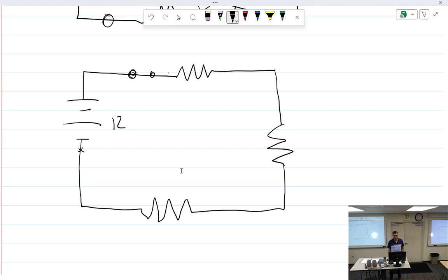But if we're measuring it from here to here, then we're measuring voltage drops: the difference between what the voltage is over here in this area versus the voltage over here in this area. So really think that through and try to get that into your mind: it's the difference between here and there. Because the next thing is people go, wait a minute, what if I'm measuring it going this way instead of the other way? Well, it'd be negative if you just swap the leads, but so what? It doesn't matter.